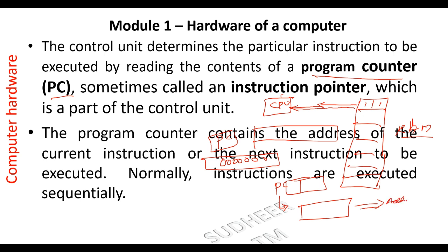What is the address bus for? It is for carrying the address to the memory unit. The program counter content will be thrown out of your processor through the address bus. That address bus is physically connected to the address bus of the memory, so that particular RAM locations will be activated. Then our control unit will issue the read signal. After reading, the content of the memory cell will be available on which bus? The data bus. It will be available on the data bus.